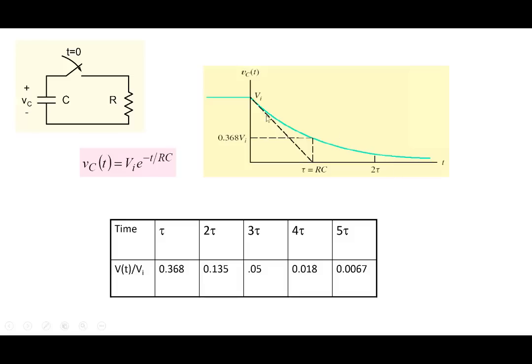And if you really want the capacitor to fully discharge or very close to full discharge, maybe you have to go to at least more than 3 tau. So you may have to go to 4 tau or 5 tau. At 3 tau, it is 95% discharged. So there's still 5% charge remaining on the capacitor, right?